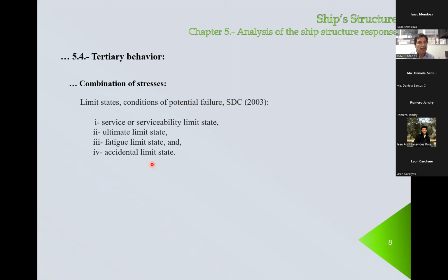Okay. Fatigue. There are many pieces of the structure where the loading is very low, but this load is applied with a changing sign like this. Trick, track, trick, track, trick, track. So this allows the fatigue to develop. That reduces the strength, generates a little crack. This little crack grows, and eventually this crack is so large that the structure doesn't have enough strength and fails.